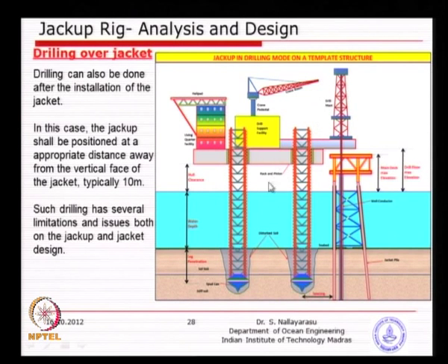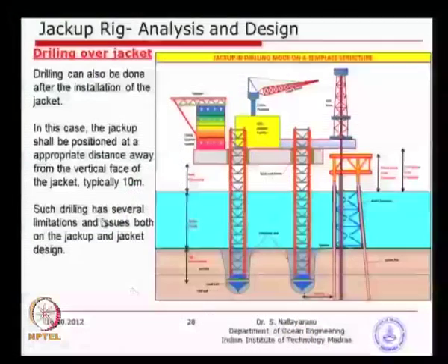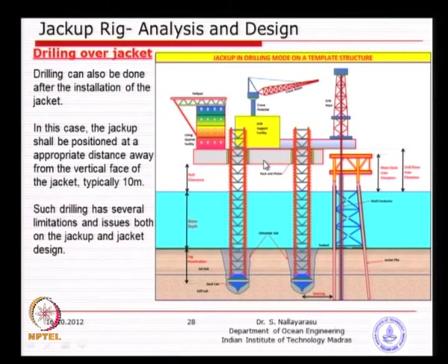You will also see in this picture several notations. See here, in this particular case on the right hand side, the elevation of the deck. You cannot have a big deck structure 50 meters high and want to put the jackup on top, which is not feasible, because we cannot jack up this hull more than 15 to 20 meters. So whenever you are having a drilling operation by a jackup, these structures need to be designed sufficiently low so that the jackups can come and do the drilling, typically about 20 meters, 25 meters, and most of the jackups cannot go beyond 25 meters.